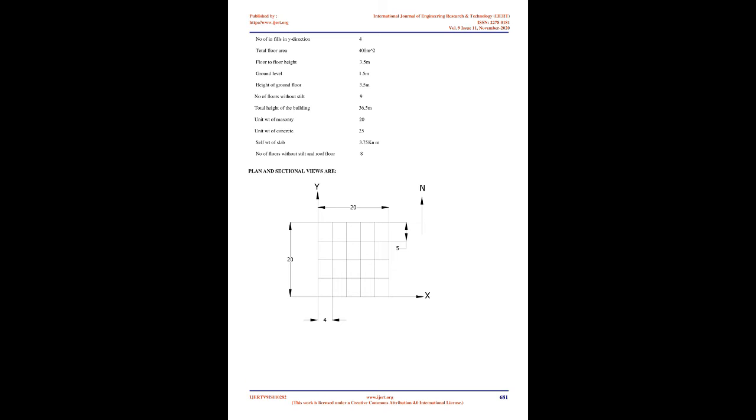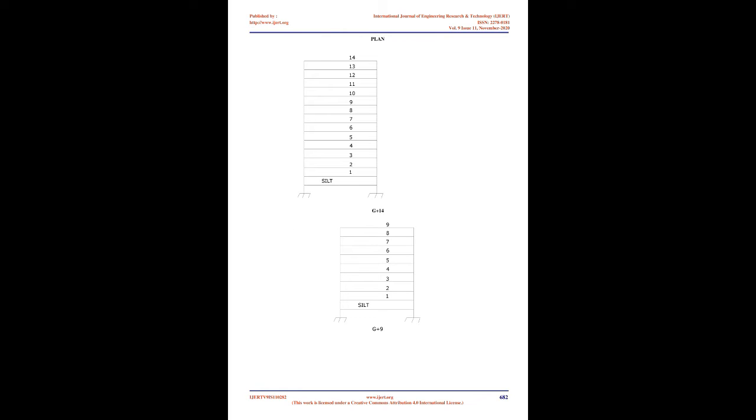Seismic design involves two distinct steps. 1. Determining, or estimating, the earthquake forces that will act on the structure. And 2. Designing the structure to provide adequate strength, stiffness, and energy dissipation capabilities to withstand these forces. 1.2 Behavior of structure.